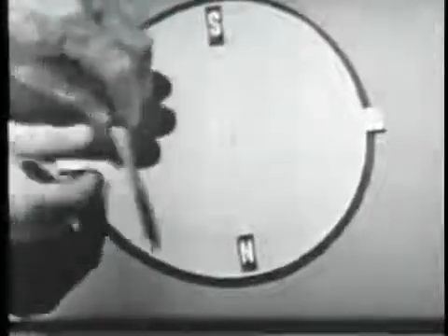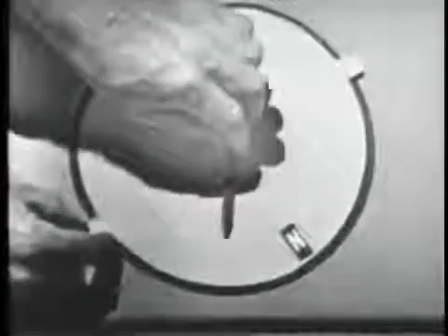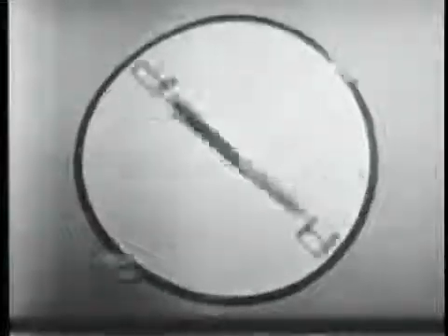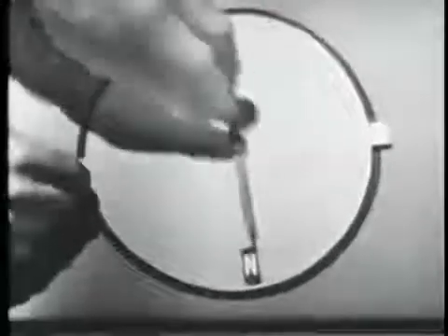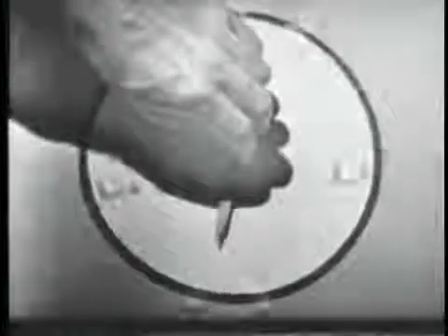Now, the principle we want to show you here is that if we take another magnet, such as this compass needle, and put it on the pivot, in other words, so it's free to rotate, and we spin the cardboard disc, we have a rotating magnetic field. Now, you'll notice that the compass needle picks up the rotation of the rotating magnetic field, tries to align with it. Now, this is an extremely important principle. Let me show you that again. We have a rotating magnetic field, we have a compass needle. Look at it pick up the rotation of the rotating magnetic field.